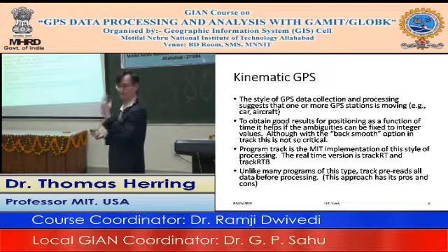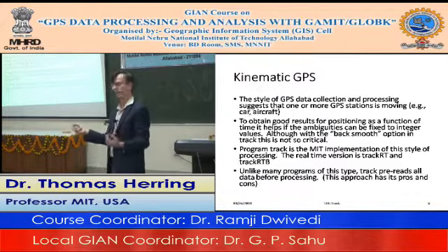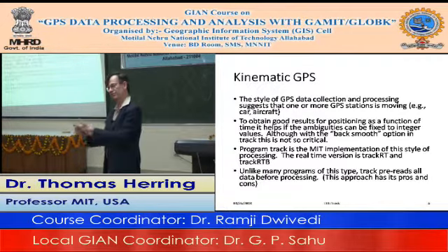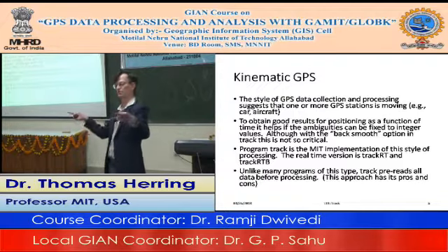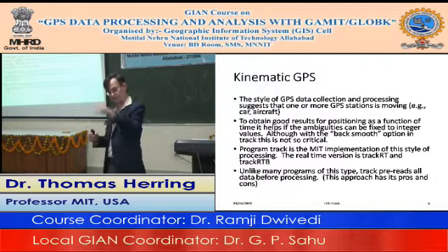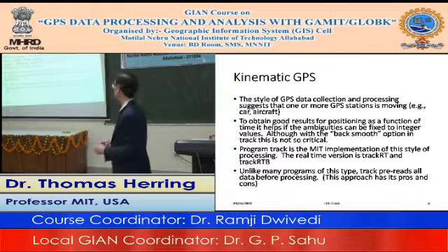Track is also a Kalman filter, the same as GLOBK is, so it has a smoothing filter in it, and you invoke that with a command called back, and it just says back smooth. And what that does is, even if you have not resolved ambiguities, when you're getting the trajectory out, the ambiguities are at least fixed values. Whereas if you do it in the forward kinematic mode, the parameters evolve and things are changing. So it produces a much better quality solution.